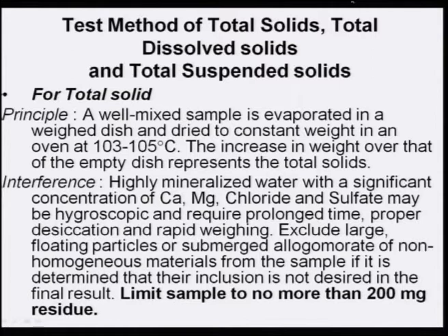Exclude large floating particles or submerged agglomerates of non-homogeneous material from the sample if it is determined that their inclusion is not desired in the final result. Limit the sample to no more than 200 milligram residue. So, that means that any sample should not have more than 200 milligram of total solids, otherwise that sample requires